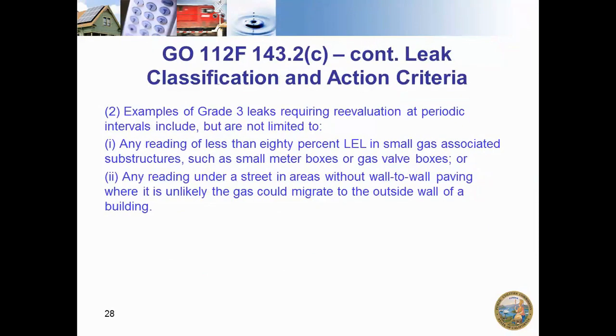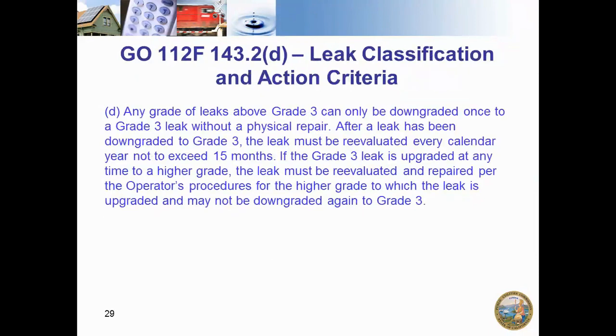So some examples: reads of less than 80% LEL in small gas substructures, such as meter boxes or gas valve boxes, or any reading under a street in areas without wall-to-wall paving, where it is unlikely to migrate anywhere dangerous. And so you can regrade your leaks.